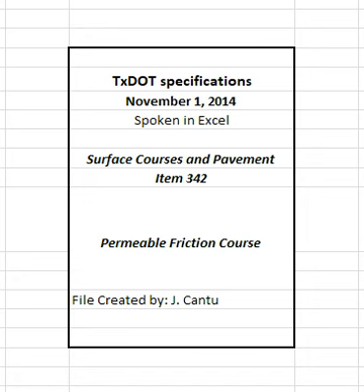4.4.2.2.9 Approval of JMF3 and subsequent JMF changes. JMF3 and subsequent JMF changes are approved if they meet the mixture requirements shown in Table 2 and the master grading and binder content limits shown in Table 4, and are within the operational tolerances of JMF2 shown in Table 5.